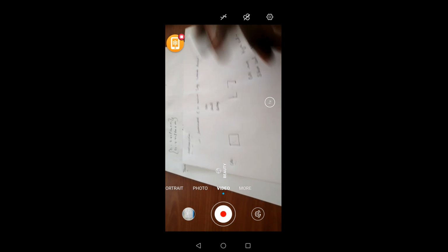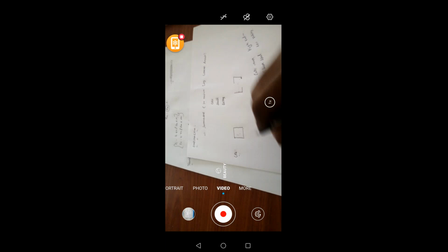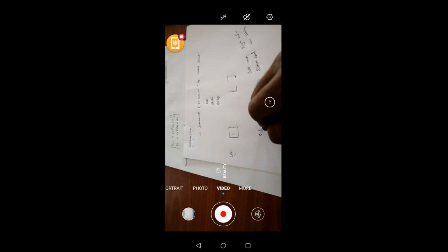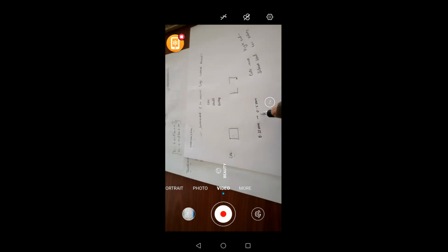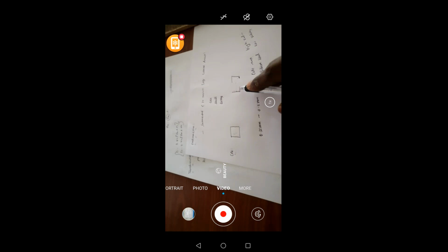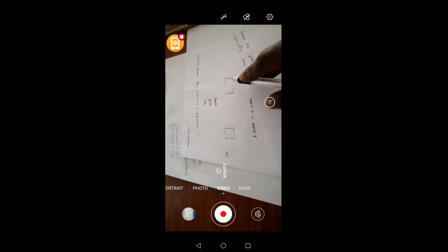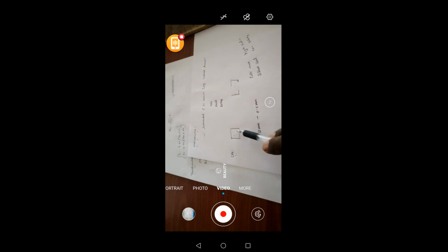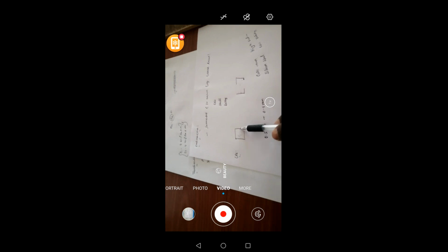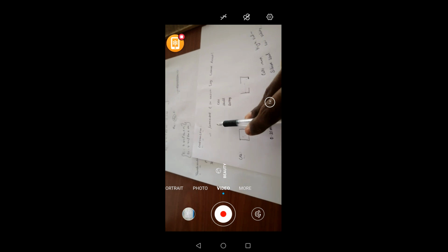The thickness of the plate is 0.35 mm to 0.5 mm. Each plate has to be bunched together, and finally we get the structure like this. This structure has laminated construction, and it is used to reduce the eddy current losses.